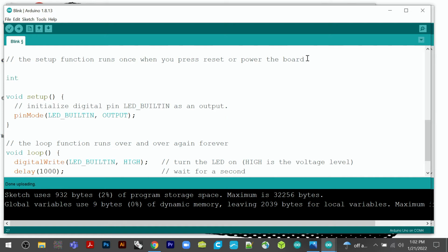A global variable, and this is an integer variable. We'll talk more about this meaning as we go. Again, this is crash course. We want to move fast. Integer variable, let's call it LED pin equals pin 8. And then at the end of the line, this is a syntax issue, we're going to add a semicolon. So what this line means is, well, let's just add a comment.